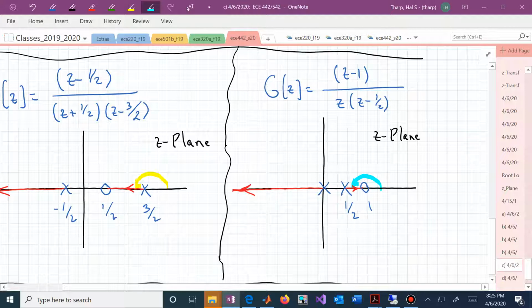Any point to the left of the imaginary axis, or on the left-hand side on the real line, belongs to the root locus because we have the 0's angle of 180. We have a pole having an angle to that point, which is 180. Those two subtract and essentially cancel each other.